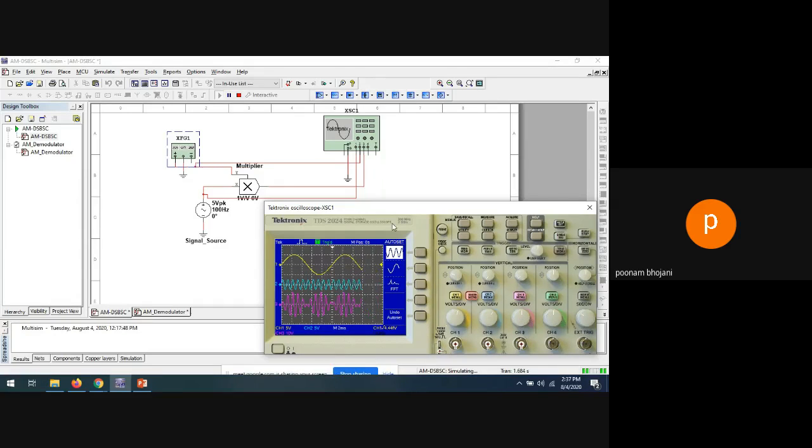Okay. So if AM equal to AC, then see the amplitude is reaching the zero line after every one cycle of the sine wave. So AM equal to AC means modulation index equal to 1, and modulation index equal to 1 means it is the perfect modulation. So you will get AC minus AM equal to 0. So your envelope reaches the zero line. Again it starts with the positive cycle, again it reaches 0, and so on. Same for the negative envelope.